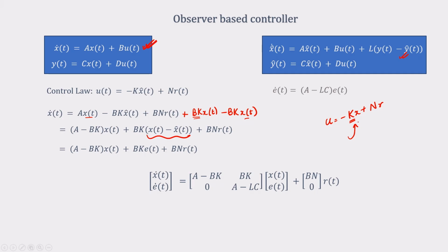Because doing that you were controlling the rate at which the states will be evolving, because the eigenvalues govern the rate at which the states evolve. And I can design an L here separately, which will help me to come up with an observer such that the x and x hat converge to each other as fast as we want.